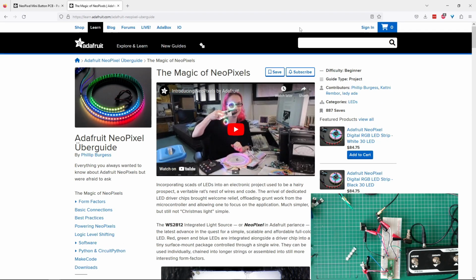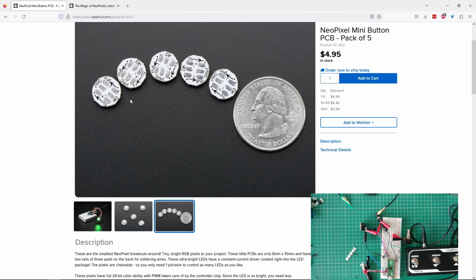But as I said, the main thing is you have power, so positive end, negative end. Ignore this 5 volt for now. Ideally they would be powered from a 5 volt supply, but we can do that with 3.3, getting them directly out of the Raspberry Pi Pico. And we have data in and data out. So you can go from a microcontroller to data in, data out goes to the next Neopixel, data out goes to the next Neopixel, and let's see how that works.